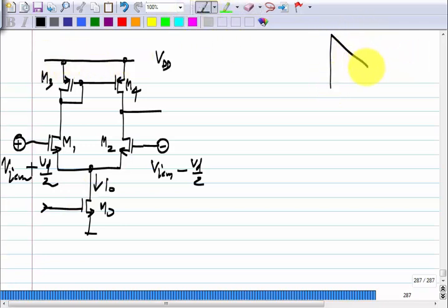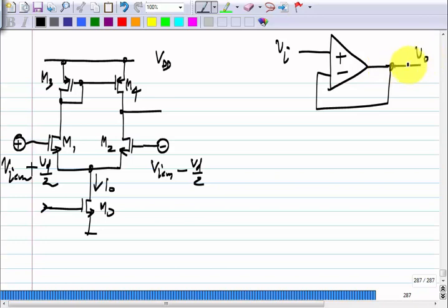let us try and make a voltage follower with an op amp, which is a voltage controlled voltage source of gain 1, or a unity gain non inverting amplifier. So, if I have Vi here, this incremental output should also be the same as the incremental input, that should be equal to Vi. So, what should we do in our op amp to make this connection? All we have to do is connect it up like that. And here we apply the input signal Vi.